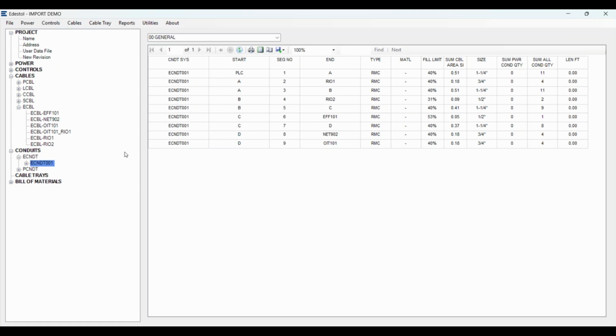cable goes through. So you now have an ability to just drag and drop and create those riser diagrams, or I actually kind of call them conduit schematics or whatever you want to call them, but you have the functionality as either a contractor or an engineer or an estimator to literally define your entire raceway system from a conduit sizing standpoint.